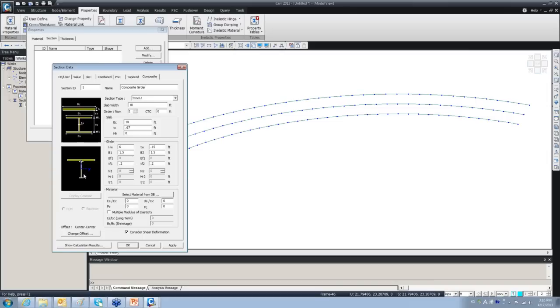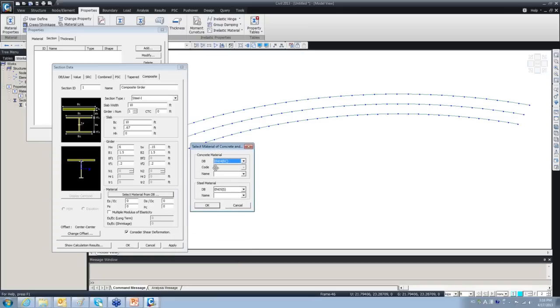So now when you have a steel and a concrete, definitely we have to calculate the equivalent sections, and then find the location of centroid and all those sectional properties. For that reason, the software gives you this box here for the material. If you click on that, it gives you an option to select the material type. So I'm just selecting ASTM.